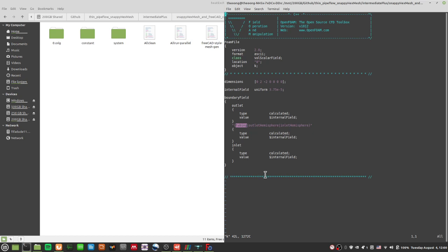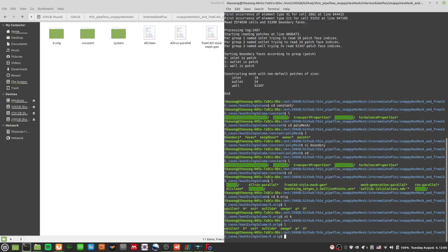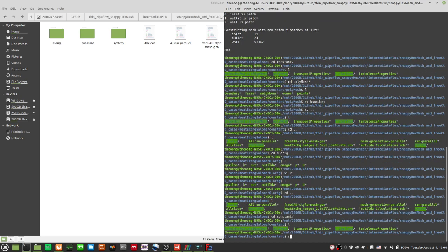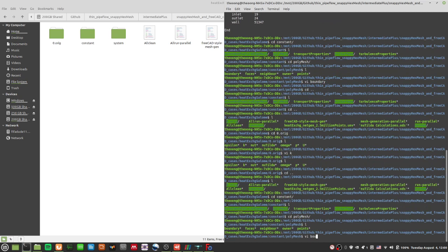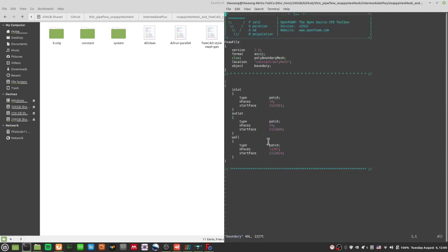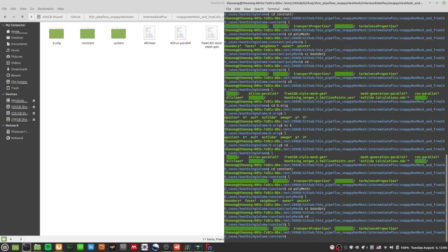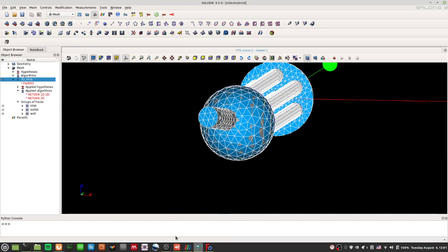That's fine. I also have to change the boundary type for walls from patch to, let's say, wall, so that we can use the create patch dictionary, the create patch utility to do that. I've already went through that in a few videos prior, so I'm not going to go through it again. So that's basically the idea.